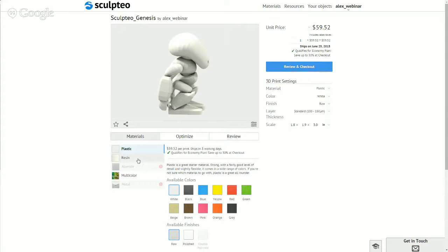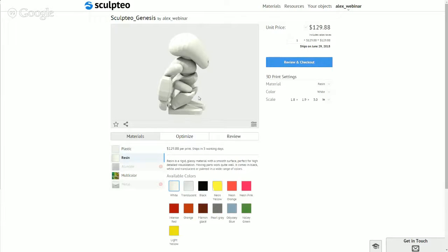However, if you're dealing with resin, you bring that down to, I think it's between 15 and 20 microns for resin. So that's a very highly detailed material. It's very different to plastic. The material properties, it's not as elastic. Plastic will be able to bend a little bit, whereas resin, think of it like dry glue. It's a bit more glassy. So if you smash it, it will shatter a bit like glass or toffee. But generally, it's solid enough. And then alumide will be thicker. Again, every material has its own thicknesses.